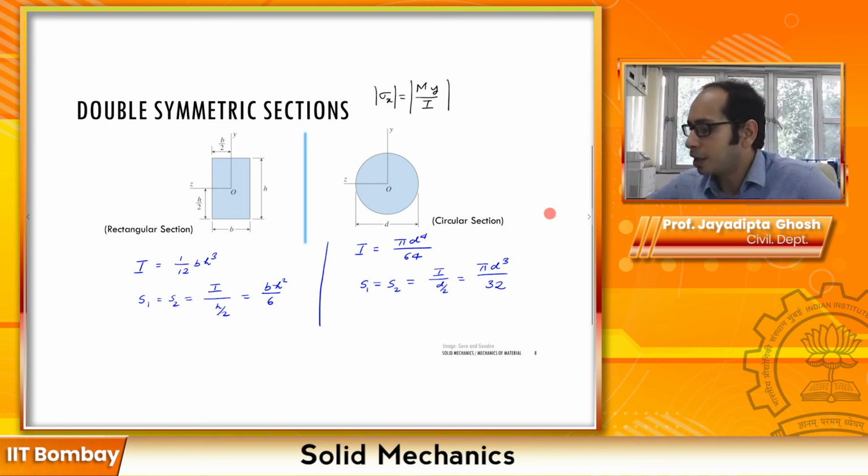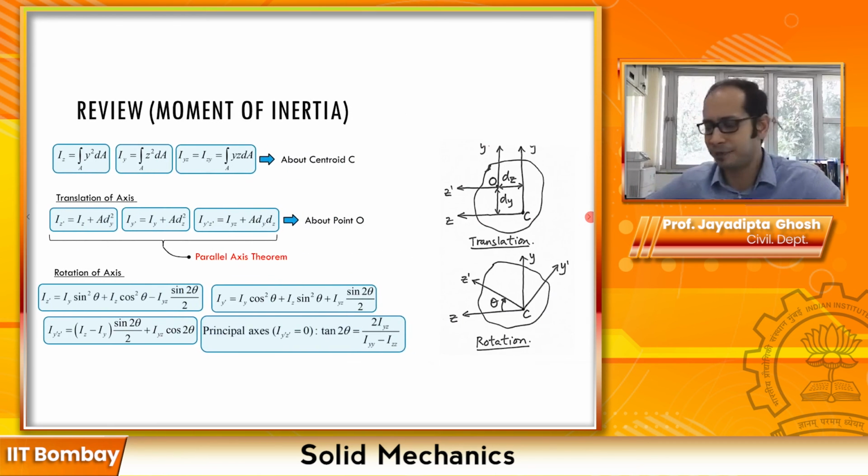Simple. Now talking about the different area moments of inertia different sections can have, these are the general formulas, which you're quite familiar with. If you are not, I recommend you flip through some of the very basic standard textbooks in your +2 or any of the engineering or mechanics of materials books. If you flip through the last pages in the appendix, you're usually given these formulas. So this is your IZ. If you have a section on the Z axis, this is your IZZ, which is the integral of y square dA, and IY is the integral of Z square dA.